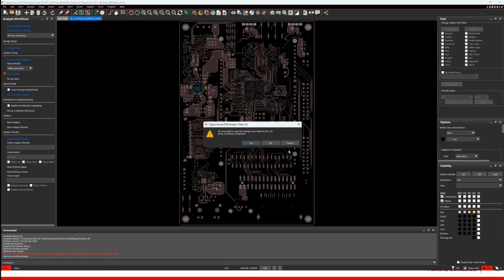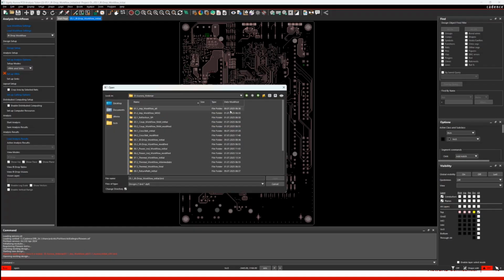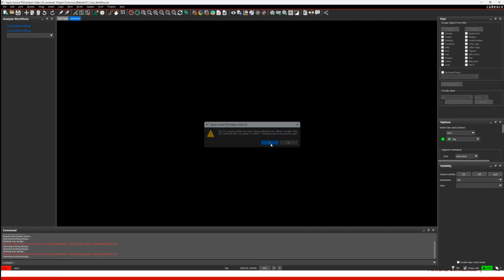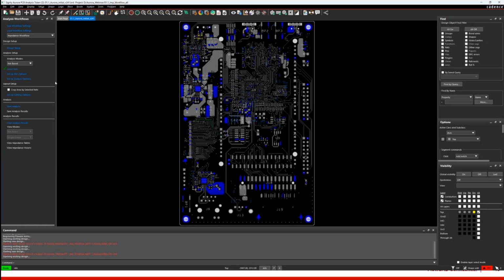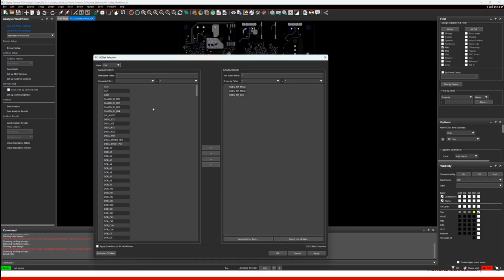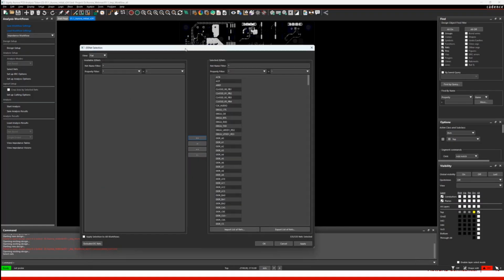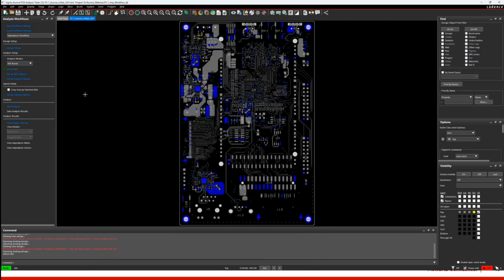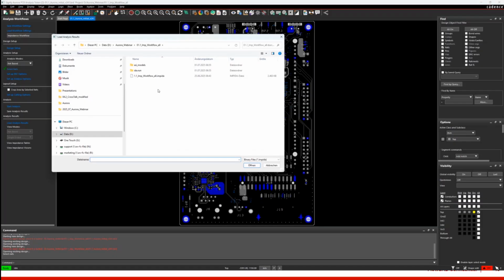I open the file. Let's start here with the impedance workflow. Oh, I don't want to save any files. Okay, start again. At first, you can select some nets. You can either select all from this list, or only some selected nets. I've done this in advance, because the simulation of a complete net list, which includes more than 500 nets, will take several minutes.